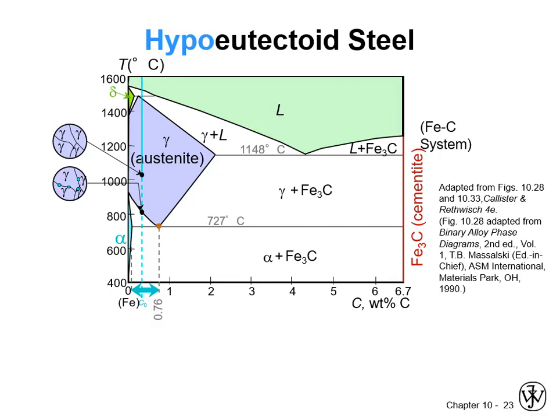In steels, one of the most important things we can do is control the size of the grains in that austenite, that gamma region, because everything that forms after will be controlled by those. It starts on them, and its eventual size will be determined by the size of those prior austenite grains.